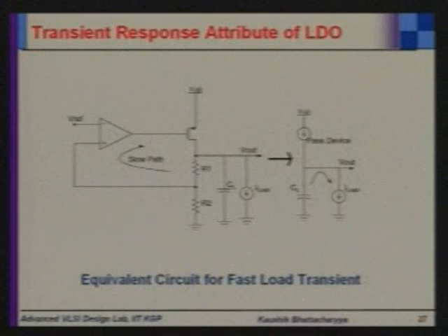But in case of on-chip power management, when the capacitor comes within the chip, at that time the capacitor value is 100 picofarad maximum or less, 50 picofarad, then that capacitor is unable to supply the necessary charge at the time of load transient, that means when current step occurs. So that is also one of the challenges, how to settle the output voltage quite quickly without small variation, small change of output voltage. So here I have shown you the LDO with off chip capacitor.